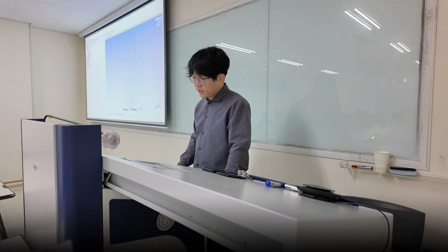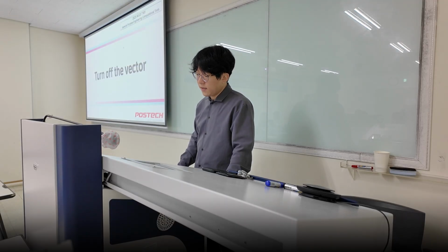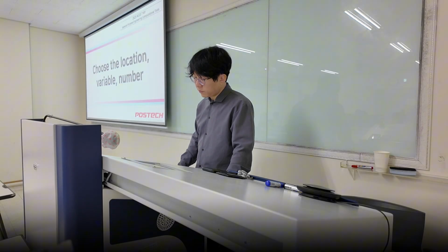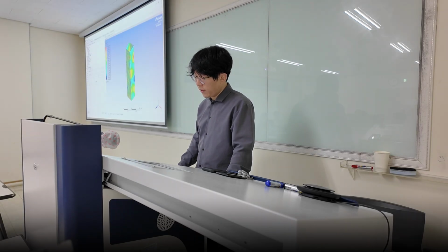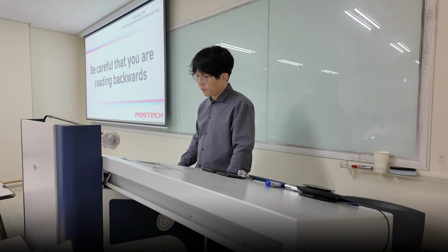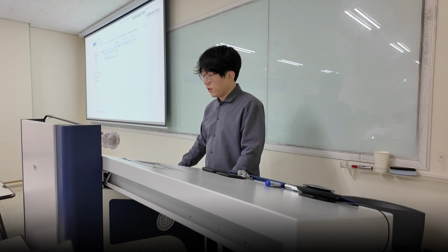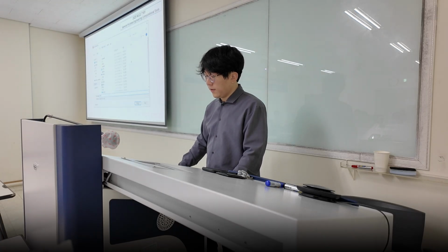Once it's over, you're going to go to the post-processing step, and then apply vector visualization so you can see where the velocity is pointing, and then you can draw the contour, and later you can also plot the pressure distribution, and you can export these values.